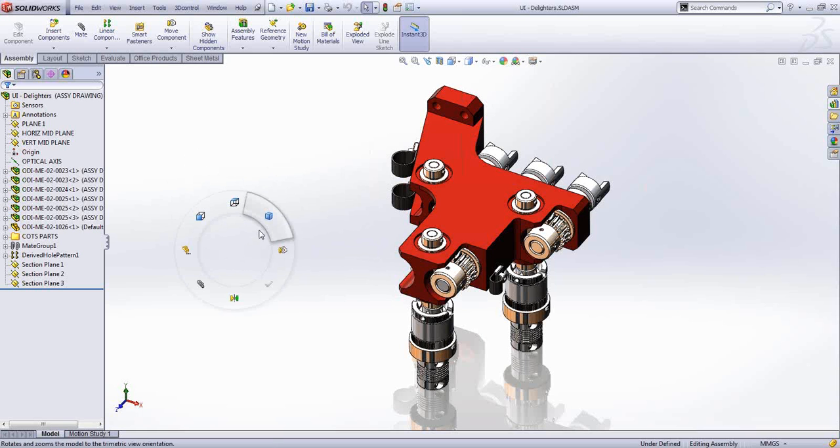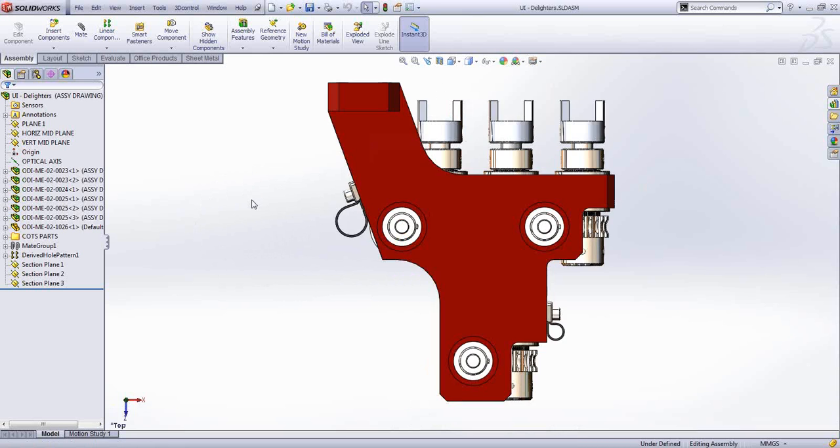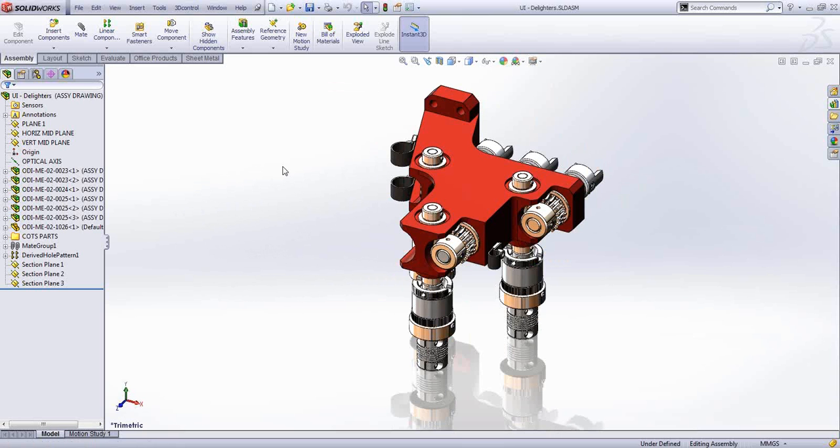It's a right click drag movement, and you have access to the frequently used commands, and it is again completely customizable. The only limitation I see here from mouse gestures to the shortcut menu is that you have a limitation of having 8 commands at the most. And again, it is different for different environments: part environment, drawing environment, assembly environment.